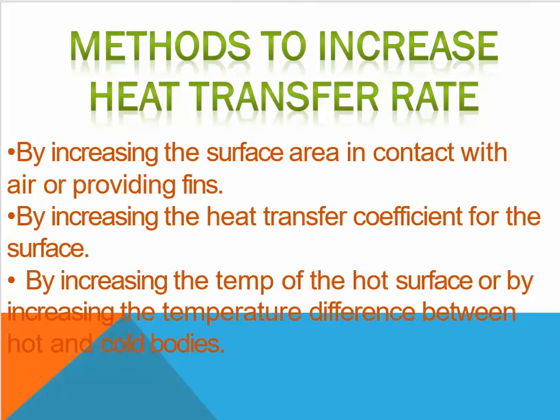Next, we will study the methods to increase the heat transfer rate. We have three methods by which we can increase the heat transfer rate. First, by increasing the surface area in contact with air, or providing fins. Second, by increasing the heat transfer coefficient for the surface.